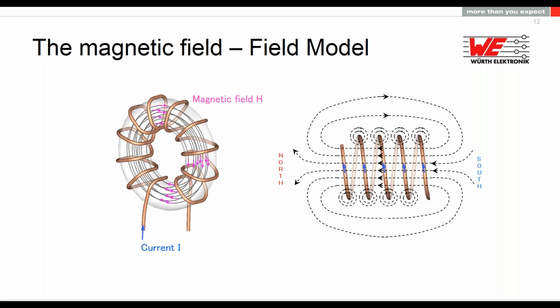south pole. Now, if you drive more and more current to this wire, this magnetic field can bend out to infinity. We talk about a rod core inductor as something like an infinite air gap inductor. Now, if you bend this rod core, and you imagine it's a rubber ferrite, because it is quite difficult to bend a ferrite, then you can build something like a circle. You build now a toroid.